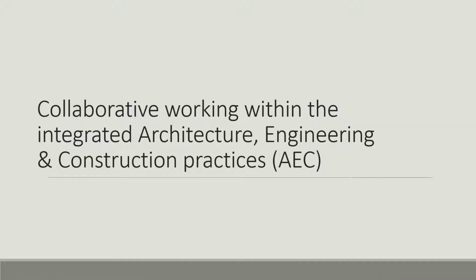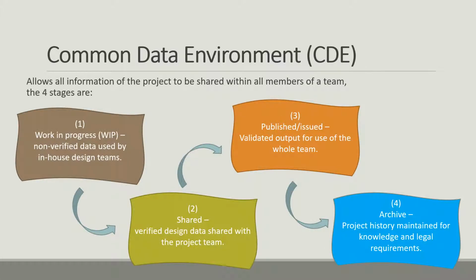Right, so this is the section on the collaborative working within the integrated architecture, engineering and construction practices, also known as the AEC. So basically between all the three disciplines there is a common data environment, also known as CDE. Basically there's 4 stages to this, and it allows all the information of the project to be shared within the members of the team. The first stage is the work in progress.